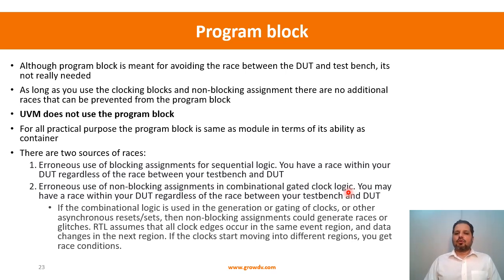When you don't do that, and you use the non-blocking statement in the combinational logic for generating the gated clock, there is a race in the DUT, which will happen regardless of whether there is a race between DUT and test bench.